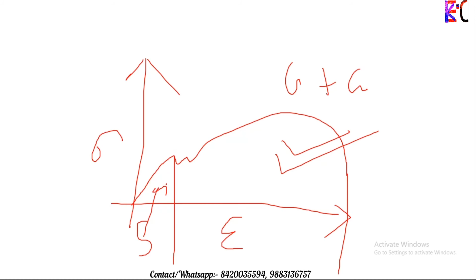So Soderberg told that always follow the linearized curve, that is till the proportional limit. That means till yield stress, that is the elastic limit. You could use till the elastic limit, the elasticity of an object. That means he told that the entire safety of the body depends on the elasticity of the body. Now Gerber told no, that you could go for the ultimate stress also. Okay, so ultimate stress, what will happen? That means he told that use this curve as your reference for designing an object.